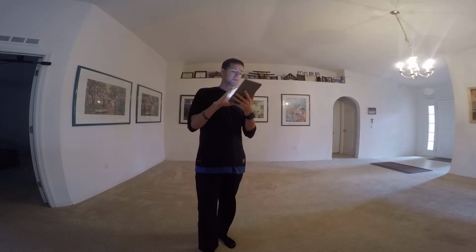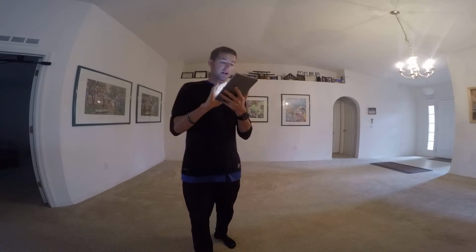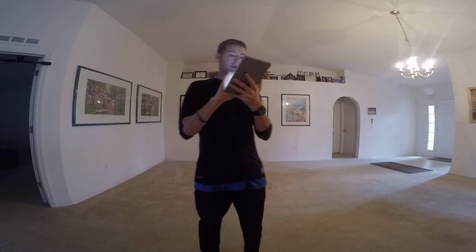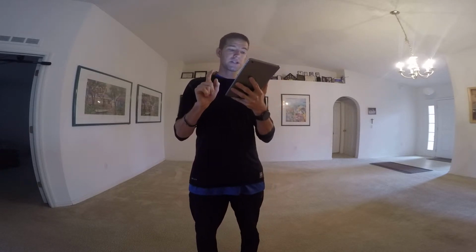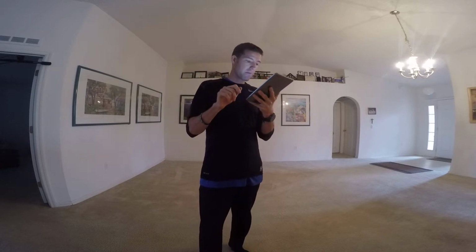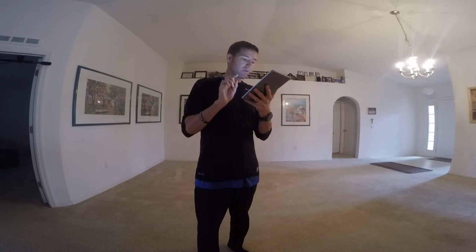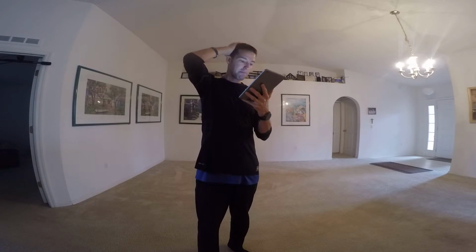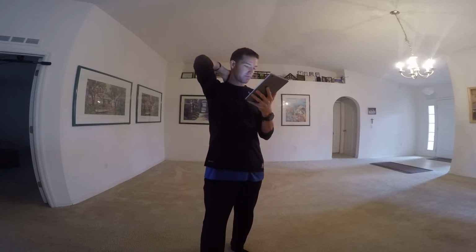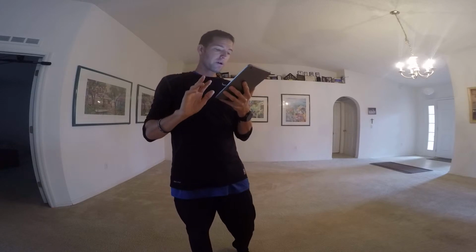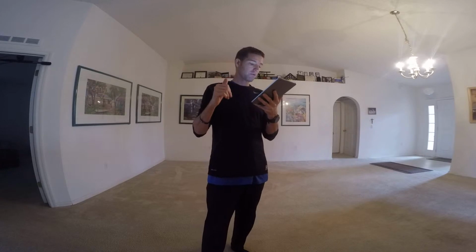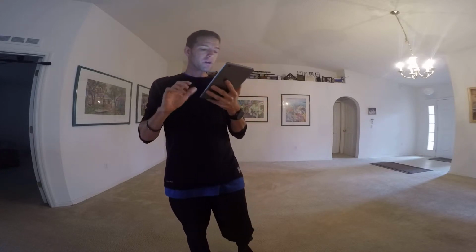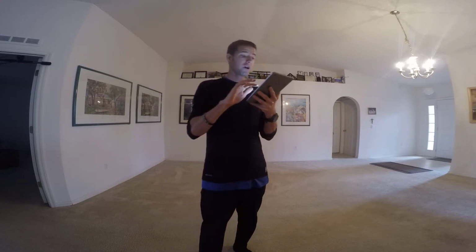Relative wind: defined as the airflow relative to an airfoil and is created by movement of an airfoil through the air. This is rotational relative wind for rotary wing aircraft and is covered in detail later. As induced airflow may modify flight path velocity, relative wind experienced by the airfoil may not be exactly opposite its direction of travel. Trailing edge: the rearmost edge of the airfoil. Induced flow: the downward flow of air through the rotor disc. Resultant relative wind: relative wind modified by induced flow.